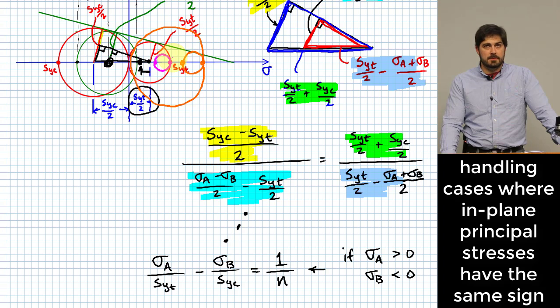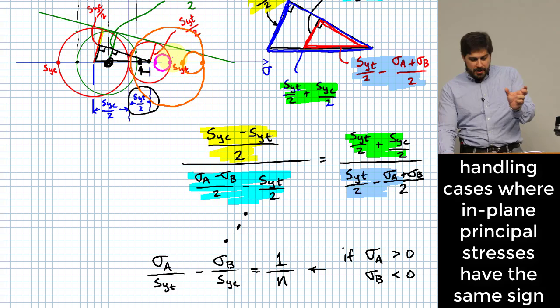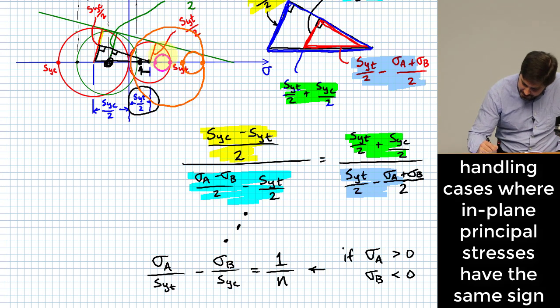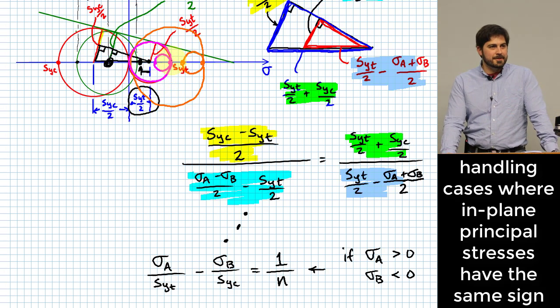Why not? Yeah, because that state of in-plane stresses implies an overall shearing stress that does this. That would be my Mohr three-circle diagram for this problem. Okay, so my maximum shearing stress is right there at the threshold.